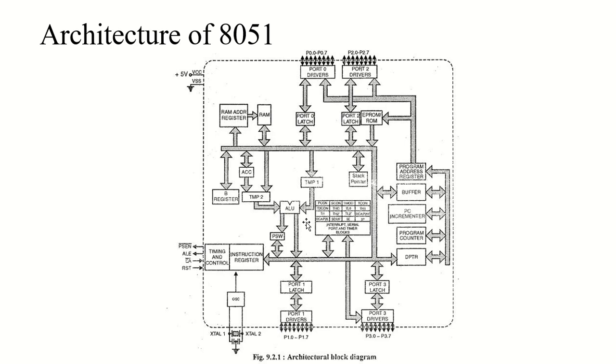If the 128 bytes of the internal RAM is insufficient, then external RAM is accessible by the data pointer, right? And in this 8051 family, external RAM of up to 64 KB can be added in any chip, but the external ROM up to 64 KB can be added to only one chip at the time of the purchasing of your controller.